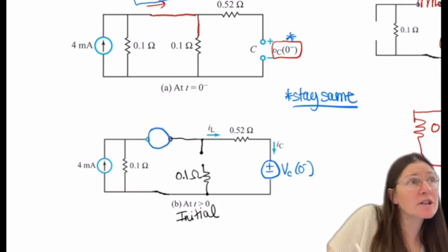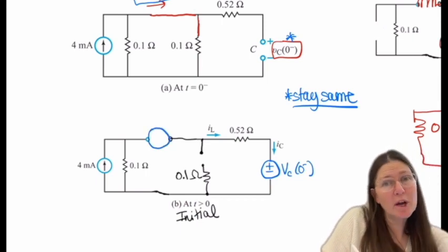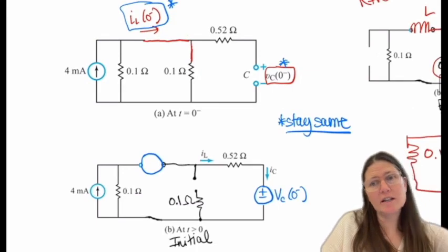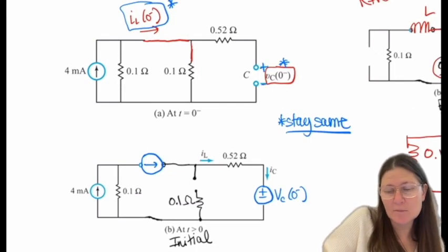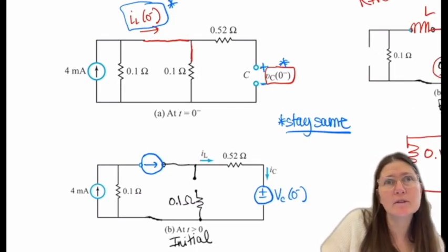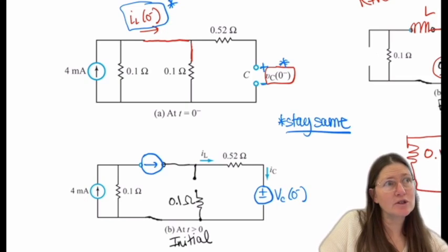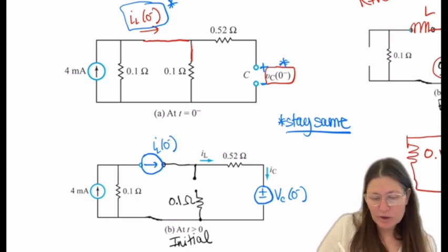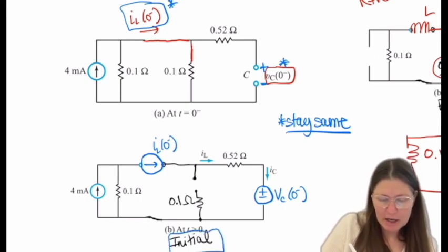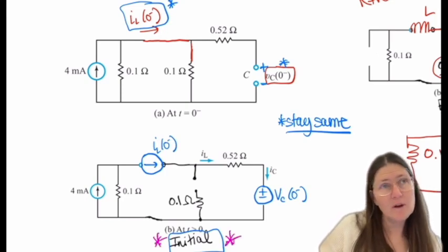And it's important in the current, whichever way you solve for the initial current, I did it from left to right, to draw the current in the same way. The polarity stays the same on the way you solve for the VC, okay? So polarities are determined by what you use to solve the initial with. And so this is the one where I get my initial value.